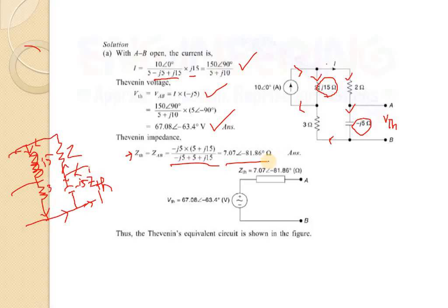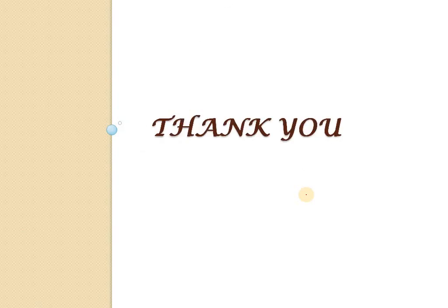So ZTH value we have calculated and VTH value also we have calculated. So this is the equivalent circuit, and in this circuit there is no load resistance or load impedance. So the terminals remain open. So that's all about Thevenin's theorem.